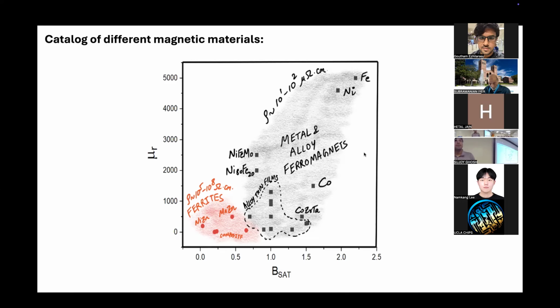When you say it doesn't go to high frequency, what's the range of frequency we are talking about? So ferrites usually are chosen for like 100 megahertz, up to tens to hundreds of megahertz. Very low. Yeah, but ferromagnetic can even go to gigahertz plus.